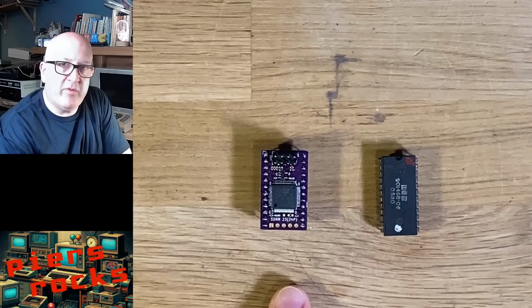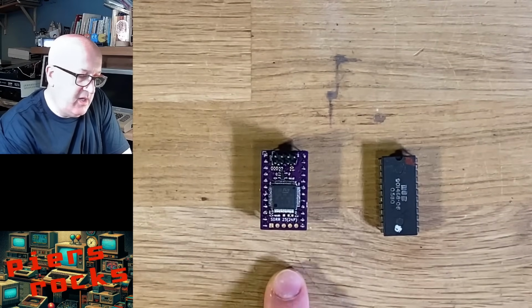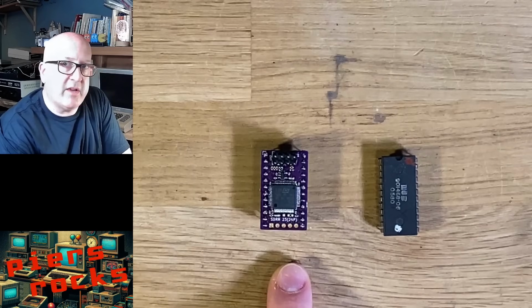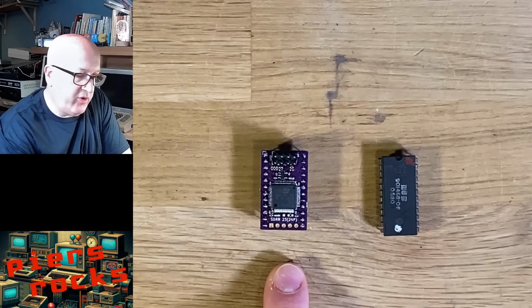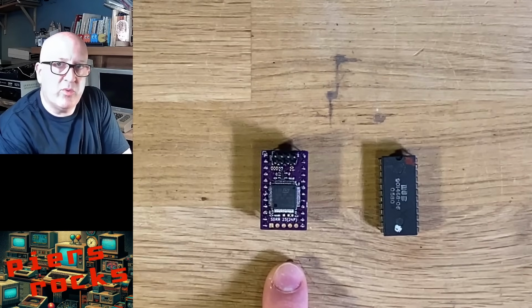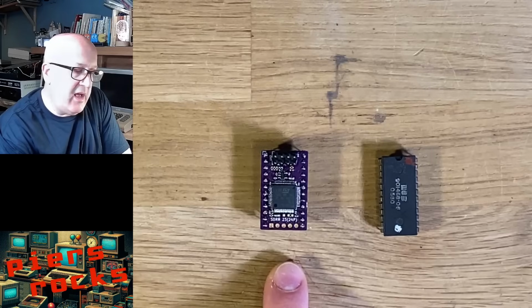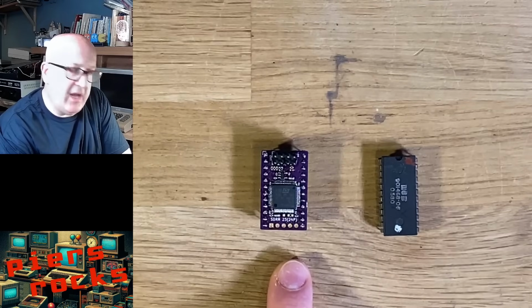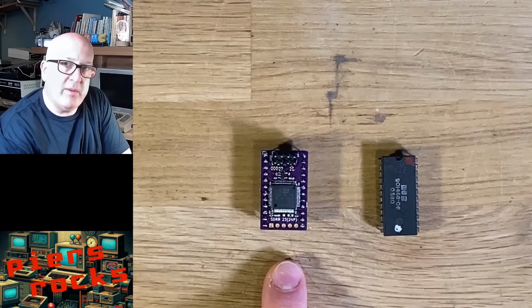So here's my software-defined retro ROM replacement. And this is essentially ultimately flexible because it's fully implemented in software. It can implement any of the different ROM types, 2364, 2332, 2316, any of the different chip select behavior combinations, and it can do it differently from multiple images that are all stored on board this chip simultaneously.